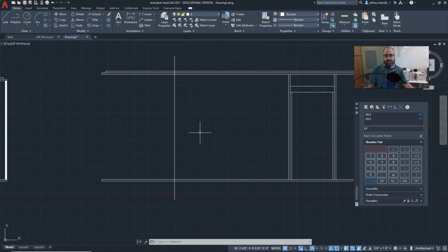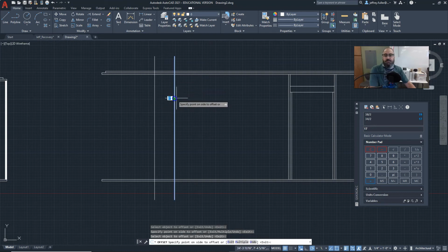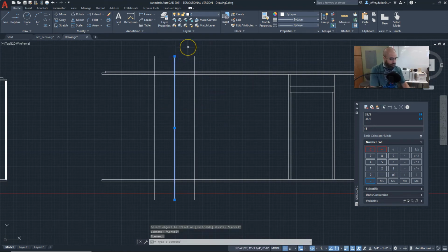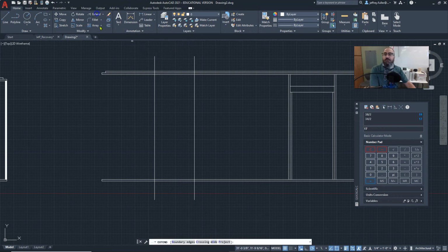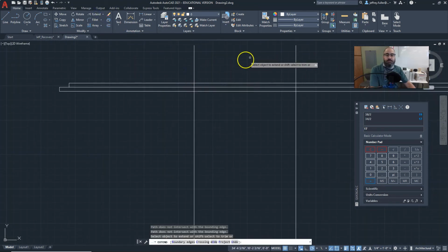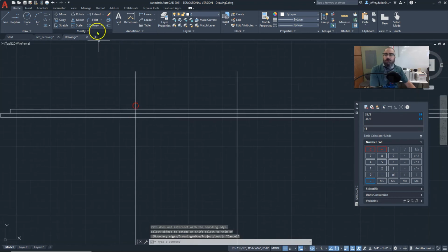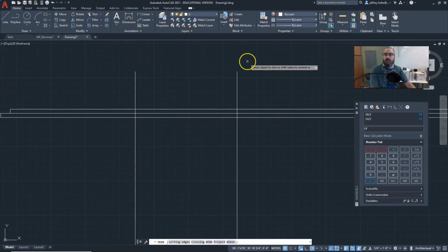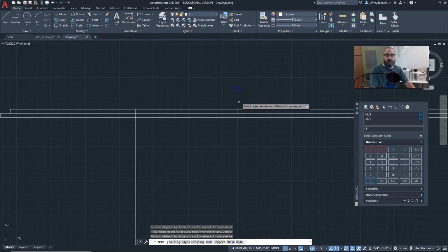So half of 34 is 17. Add 1.5 inches to that offset, and then I get 18.5. Okay, so I'm going to do an offset of 18.5 inches. And that's going to mark the inside of my king stud. Get rid of the center line. I don't need it. We can go ahead and clean these lines up. Okay, just click in there and get rid of all that.